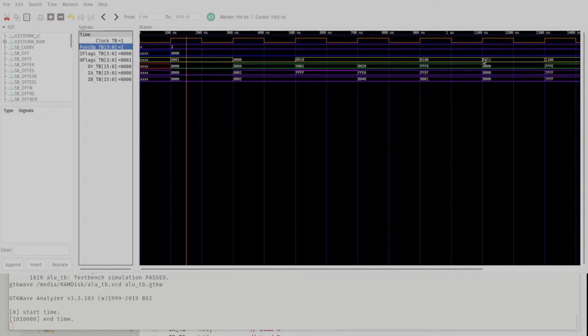The overflow makes most sense to signed values. So let's look at the final one, 7FFF with itself. This is the value we expect. We don't expect an overflow, but we get one because the sum of these two numbers causes an overflow, but it also causes the upper bit to be set, which is the negative flag, and it's not 0, and neither was there a carry. So this is the case where we're dealing with two signed numbers, and if we look at the overflow, we'll be interpreting our two operands as signed. So there you go. That's the add operation. Things are looking good, so the simulation is great.